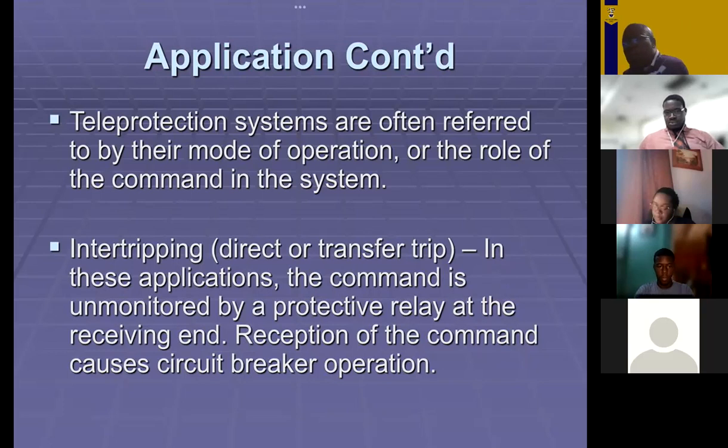So if you intend on using a direct transfer scheme, then you have to give careful consideration to the type of medium that you're going to use to convey that information. If it is susceptible to noise, then you recognize that the inter-trip scheme would not necessarily be the one that you would want to institute.